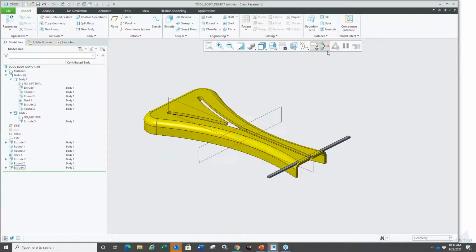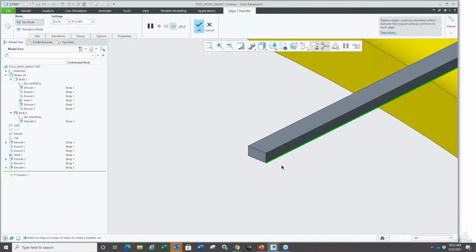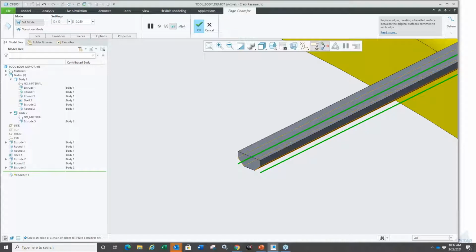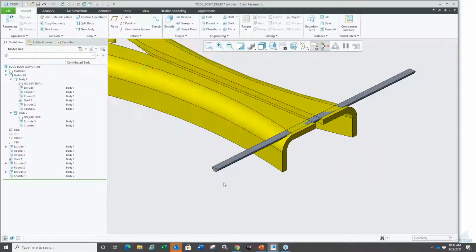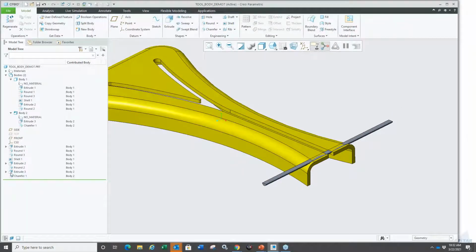There it is. And now let's add some more contributing features to this, maybe a quick chamfer in here. I could have probably added that to the sketches, but it's a good practice to break up your sketches and add them as features, right? It's feature-based modeling as always. So here, let's just give it a specific value, something like that. There it goes. This is the geometry I want to remove in here, right? That's the profile actually. And now we have two features.